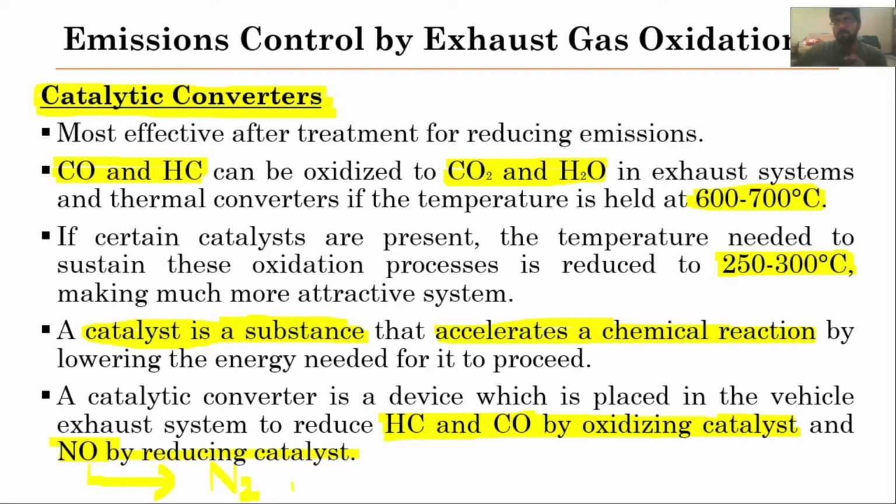So not only are they oxidizing the unburned hydrocarbon and carbon monoxide, they are also reducing the NOx emissions as well. So all the limitations of the thermal converters are being removed, are being overcome by using the catalytic converters.